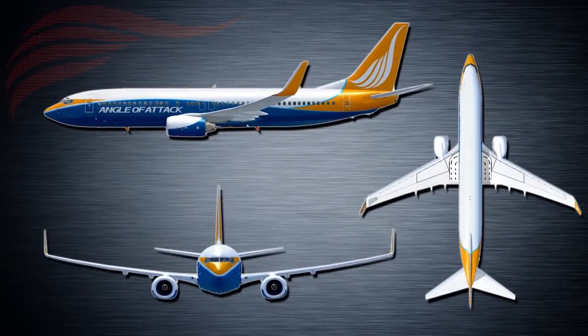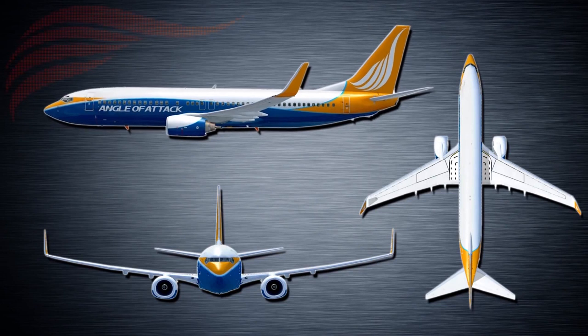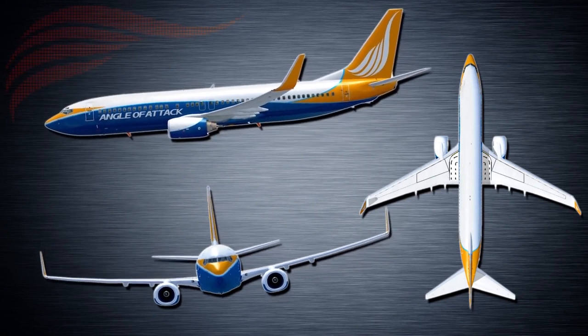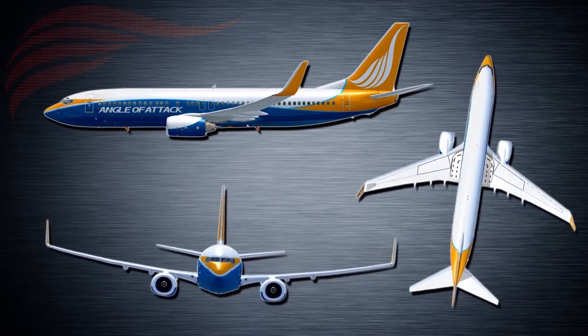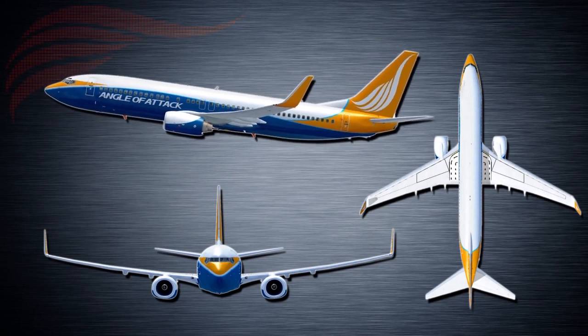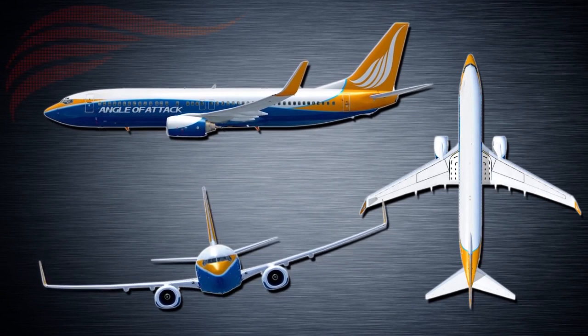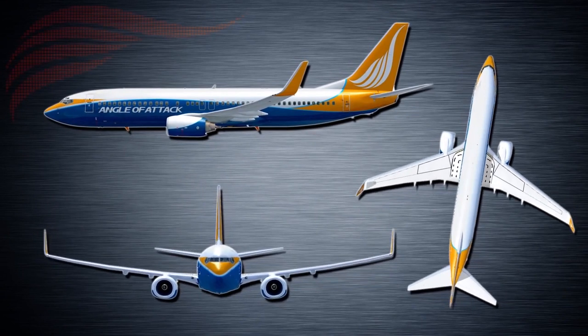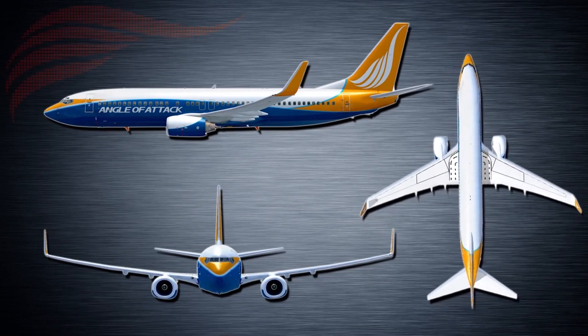An aircraft's attitude can be changed around three perpendicular axes that intersect at the center of gravity, or CG: lateral axis, longitudinal axis, and vertical axis. External forces like wind may alter the desired flight path, thus creating the need for the aircraft to be maneuvered back to the correct attitude through three movements: pitch around the lateral axis, roll around the longitudinal axis, or yaw around the vertical axis. To achieve these movements around the aircraft's axes, flight controls are employed.